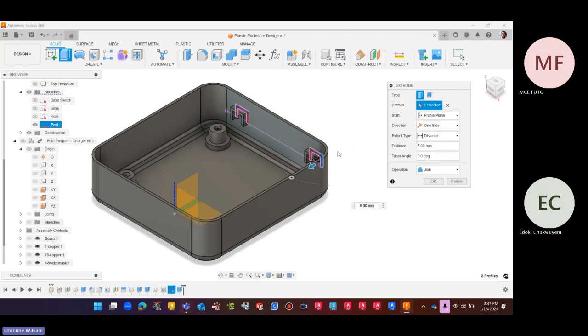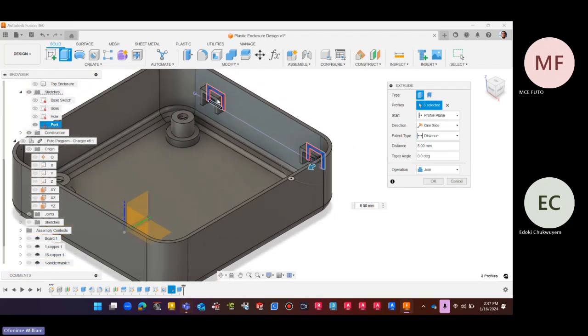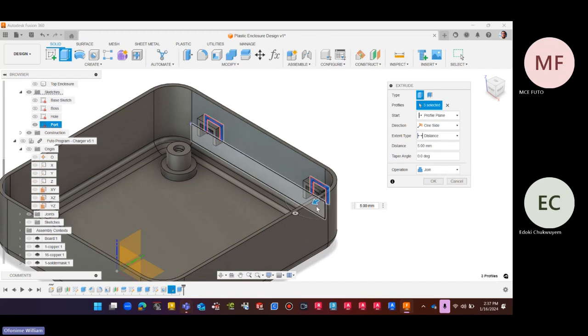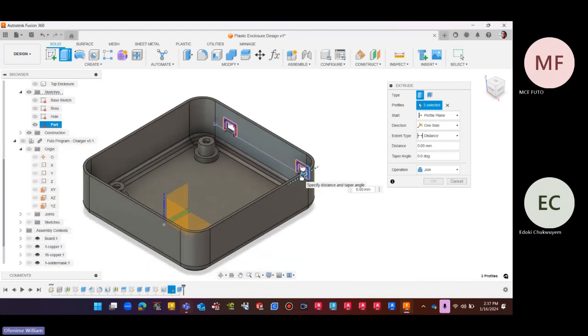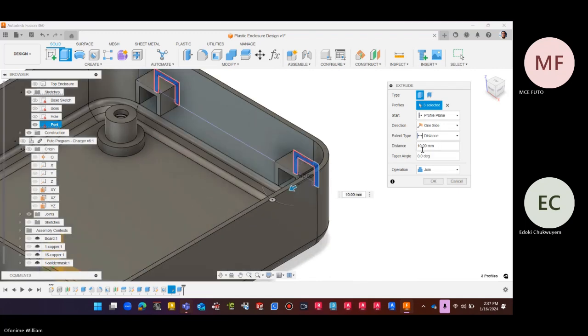Are we good? So lastly, the extent of this wall coming out, this is where the FDM rule comes in. Because you don't want to just pull this out. Yeah, it could be nice, it should be longer or shorter. But when you're going to print this out, that's when you will know if you did the right thing or not. So we're going to keep this to 2 mm.